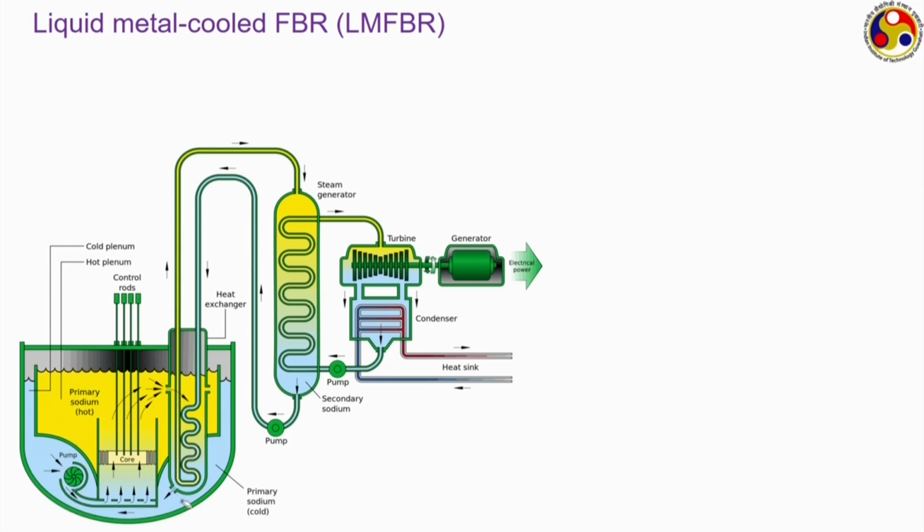The liquid sodium flowing through the secondary circuit comes via this line, gets the energy, and then goes to the other heat exchanger, which is basically a steam generator. Here on the high temperature side we have this secondary sodium, which has just come out of the intermediate heat exchanger with a large amount of energy, and on the primary side we have liquid water which comes through this pump. As it passes through this heat exchanger, it gets the energy, thereby gets converted to steam, and finally that steam comes out from here to go to the turbine and gives the electrical output through the alternator or generator.